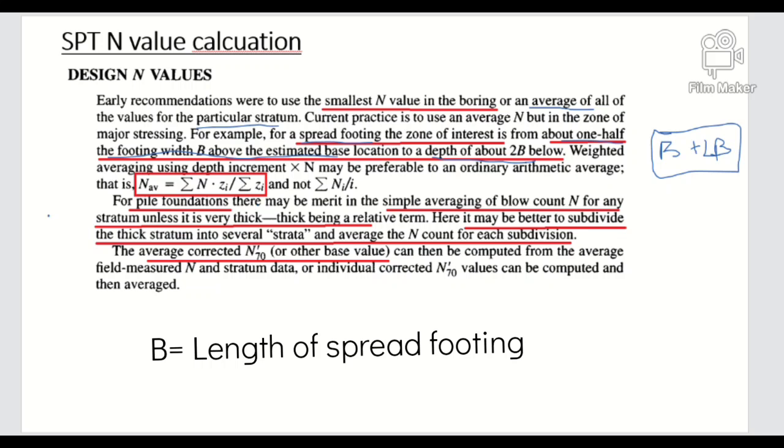Here we follow N average equal to the summation of SPT value into different depth, as per depth, divided by the summation of the different depths.